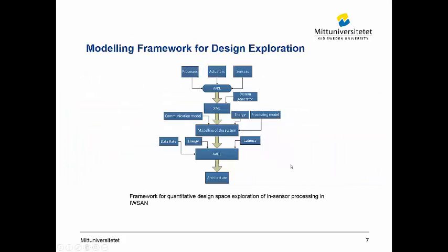So the modeling framework for design exploration is given. What we are doing is, first of all, we define processes, actuators, and sensors in AADL as you saw previously, and then we generate an XML file. It may be generated from a system generator or maybe generated manually, and from that we do the modeling of the system. Once we have the input, we can model the communication model, and we can implement the communication model, energy constraint, energy model, and processing model. After finding the optimum solution from the modeling tool, it is further implemented in AADL using the optimum solution of data rate, energy, and latency. And the hardware architecture implementation is done maybe in FPGA later on.